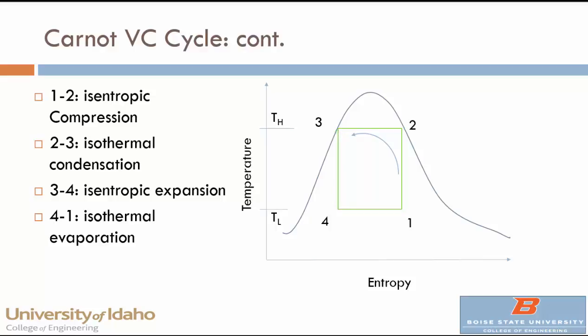isentropically, meaning that it has to be doing some work to do that, and goes back into the saturation region at the same pressure we started with, and then evaporates. It absorbs heat from the surroundings and evaporates back to state 1.